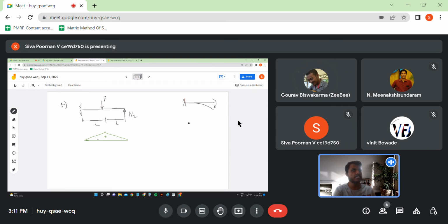Now, I can say that this free body diagram is this, right? Now I can compare it with a simply supported beam with a loading such that it has the same free body. What will be the deflected shape? Here the slope is zero at this point, is it not? Both are different points, right? The slope at this point is not zero. What is the same between them is the curvature at this point and the curvature at this point. In other words, if I take this beam and rotate it, I can get this deflected shape. Both are overlapping is what we can know, and not the exact displacements.